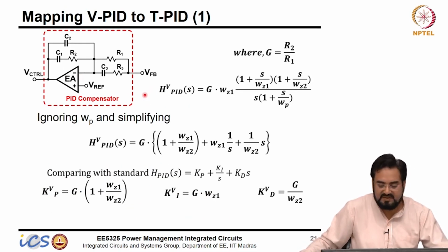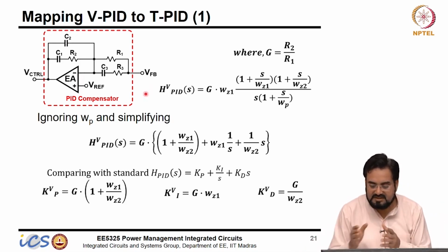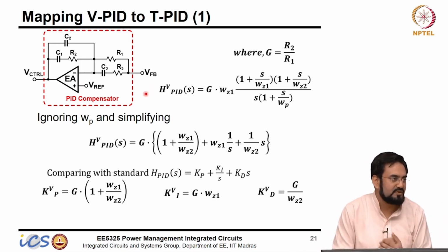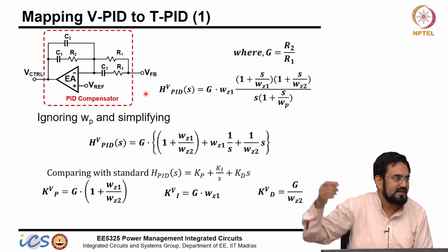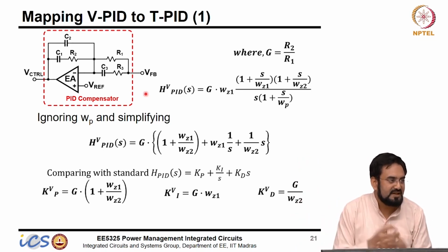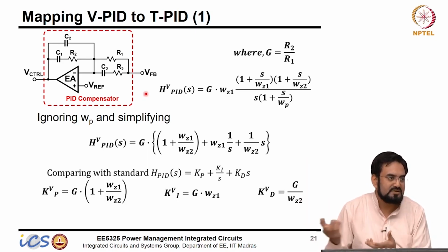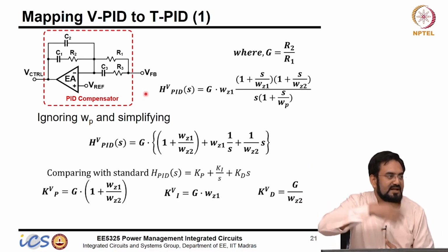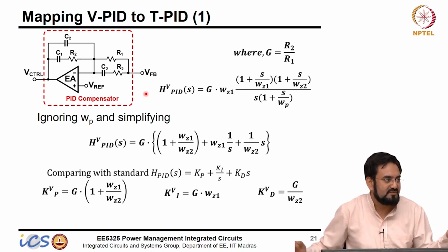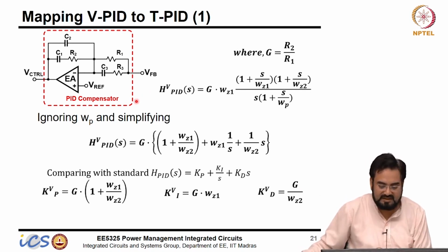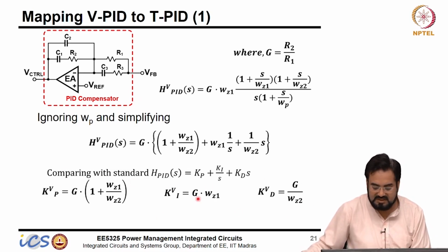So, we always look in terms of poles and zeros, we never look in terms of Ki, Kp and Kd, it becomes very difficult, we cannot understand that unless you know the zeros. Those zeros can get converted, and we know how to convert the proportional, integral and derivative components in terms of zeros. This was the equation we came up with earlier.